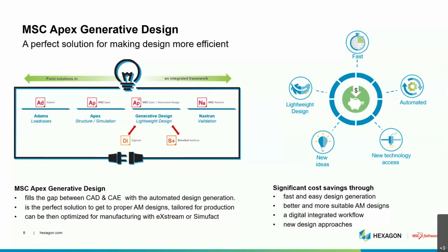What you get out is not just lightweight. This is the main purpose of a design optimization, saving weight. But what you get is as well new ideas. You get new products, you can test new things, as we have seen in the very beginning for the first bracket, where we have come from two different parts that have been mounted together and then to the primary structure. So it's a very simple part, but yes, we have changed it from this complex thing with a lot of assembling work to a one-part design that is mounted with 4 screws, and that's everything. So new ideas with lightweight designs.